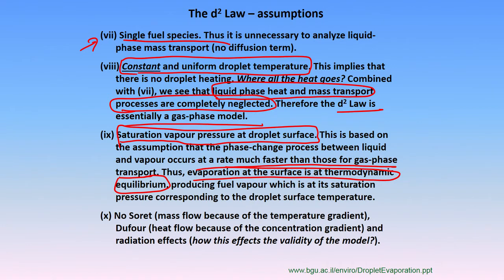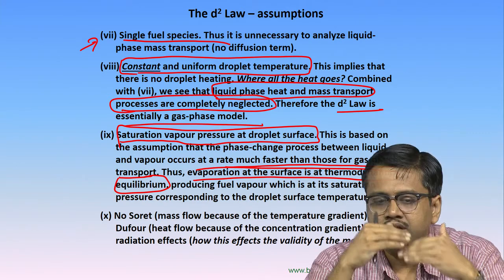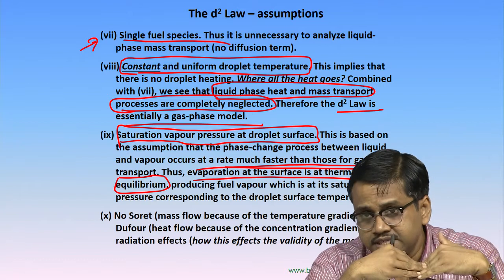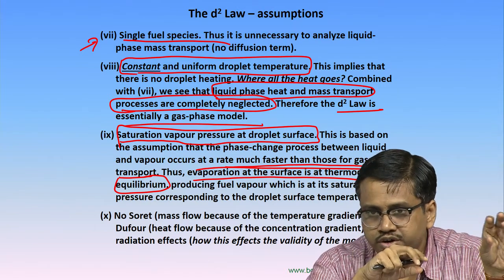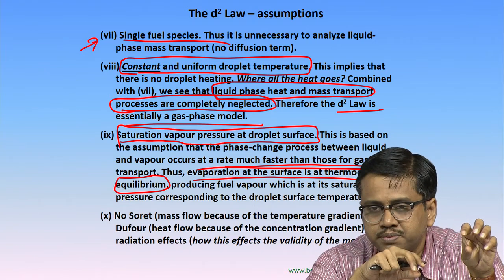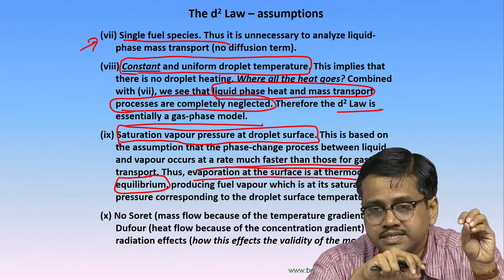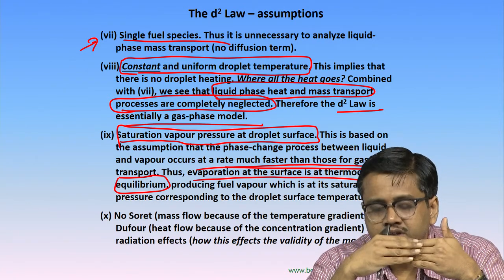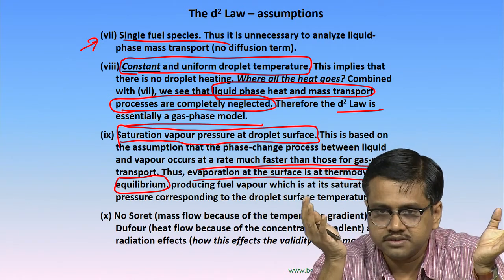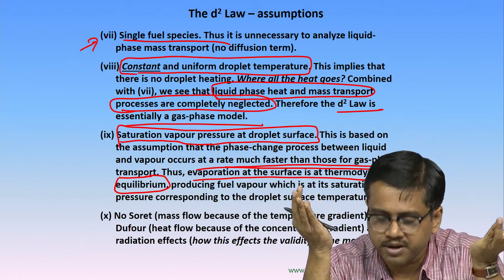There you can actually have recoil pressures and things like that. So, what happens is that we always assume that the vapor that exists at the liquid vapor interface, which you already showed exists at the saturation temperature, exists at the saturation pressure. So, that particular phase is always there. So, it is in a thermodynamic equilibrium state.